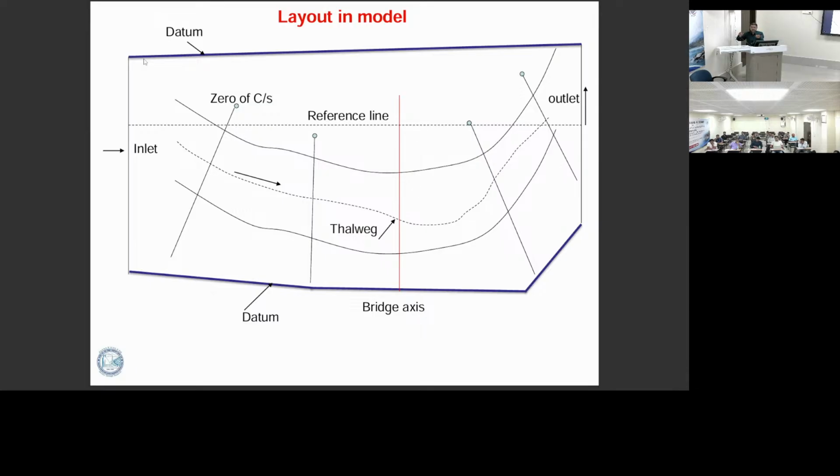As I told you earlier, the discharge measuring system should be 10 to 15 centimeters above the inlet of the model. So you know the top of the measuring system; from there take 10 centimeters below, fix the point and allot it as 105. That is called the datum, and throughout the model you have to construct it. It will be better because the datum will be the same.